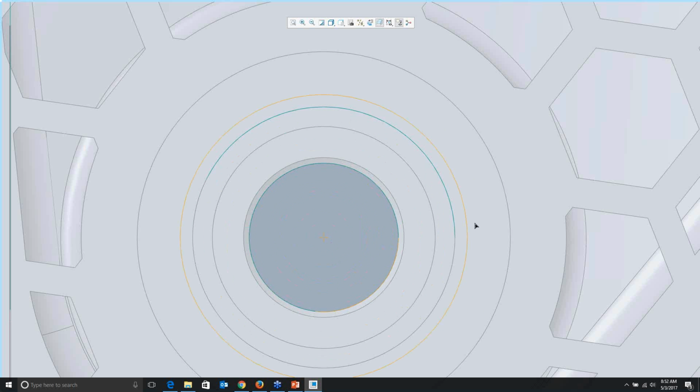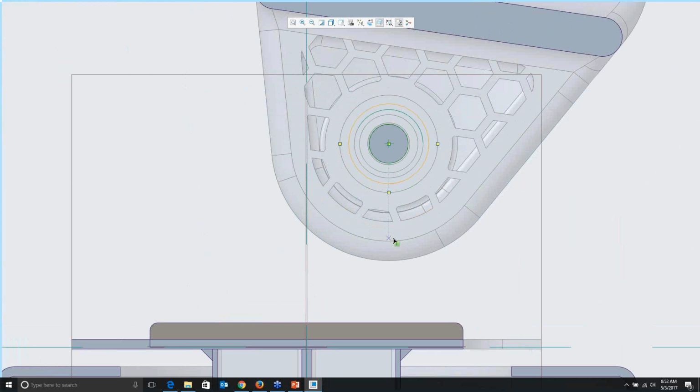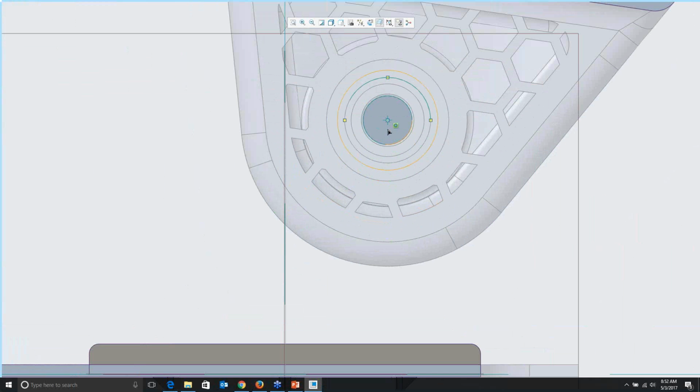Now I'll go ahead and do the same over here as well, and create a circle, I'll say probably about that size. And not only that, but you'll also notice, because that's already selected as a reference, I'm moving my mouse straight down, and it's keeping that constraint of taking that point directly in line with the center point at the top, right? I can bring it down here, and it picks the bottom plane as a reference, and I can snap to that and start to sketch on that as well, right? Actually, I should switch this to a line, so that way I can start drawing a line over here like that.